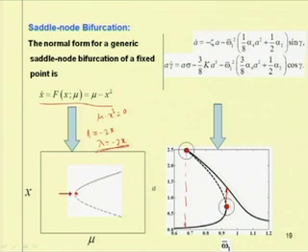So, while reducing this control parameter, from this position the system response may jump down to this stable solution. Similarly, here when we are sweeping up the frequency, at this point the system will have a tendency to jump up as this branch is unstable.